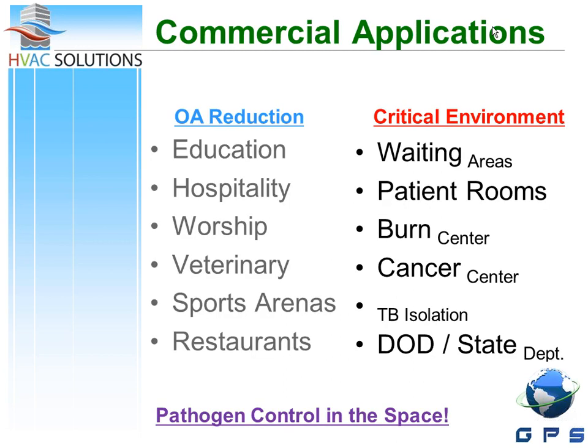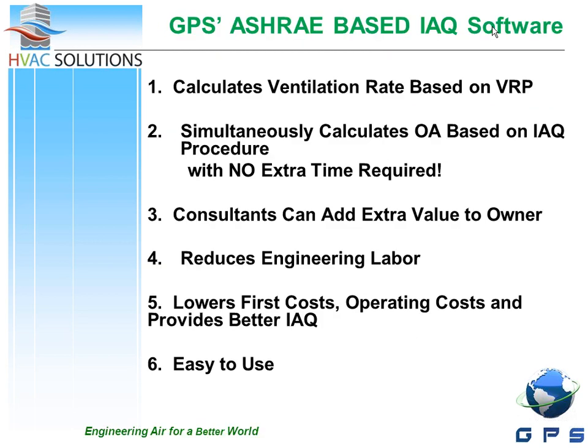The idea is that we're going to reduce the amount of outside air needed into a space. The reason being, why do we bring in outside air? Well, to dilute the pollutants. If you have an IAQ device that can get rid of the pollutants, you don't need as much outside air. So that's the idea behind it.